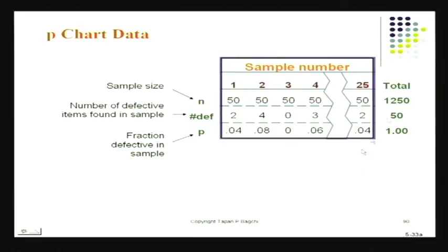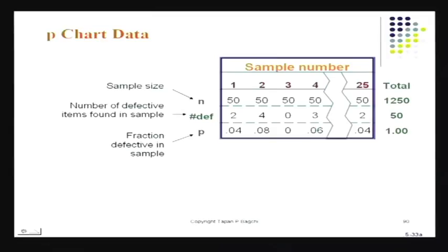When this is done, every time, like in the X bar chart or the R chart, the moment the chart goes beyond the control limit, stop the process, take a look at it, and come back and see if indeed everything is okay, or if yes, something did go beyond the set limit, and then you'd restore the process to its normal state of affairs.